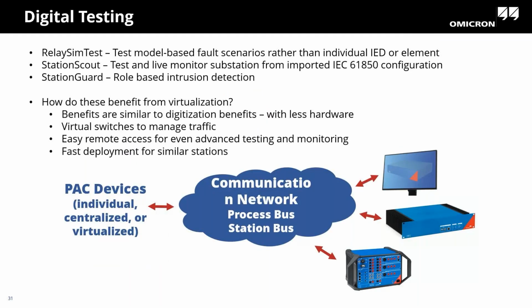Yeah. So in terms of what that looks like in realistic scenarios, we have a few different products that really benefit from this. One of them is Relay Sim Test. That is actually a modeling-based protection testing approach. So why this is something that's enabled from digital communications is because with a traditional injection test set, you have to go to each place where you want to inject, and they can be physically separated by large distances. So you might need multiple pieces of test equipment, and then you might need to synchronize all of those. And it's definitely possible to do, but it's an undertaking.